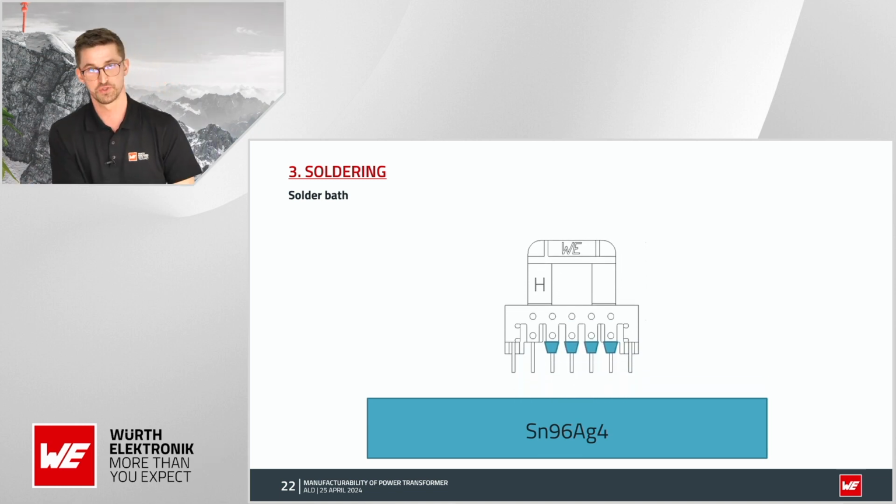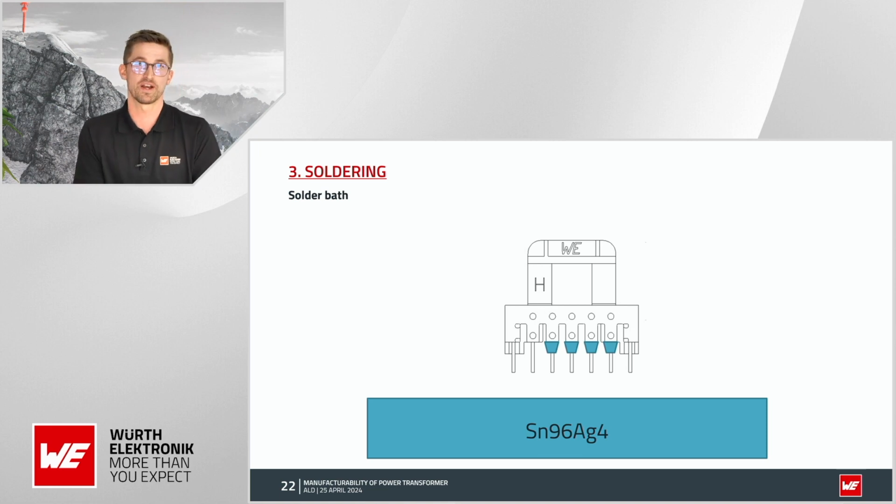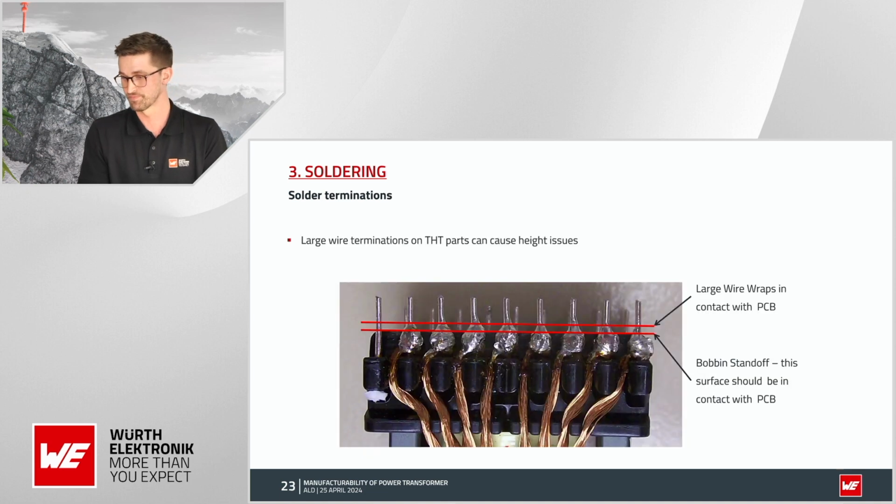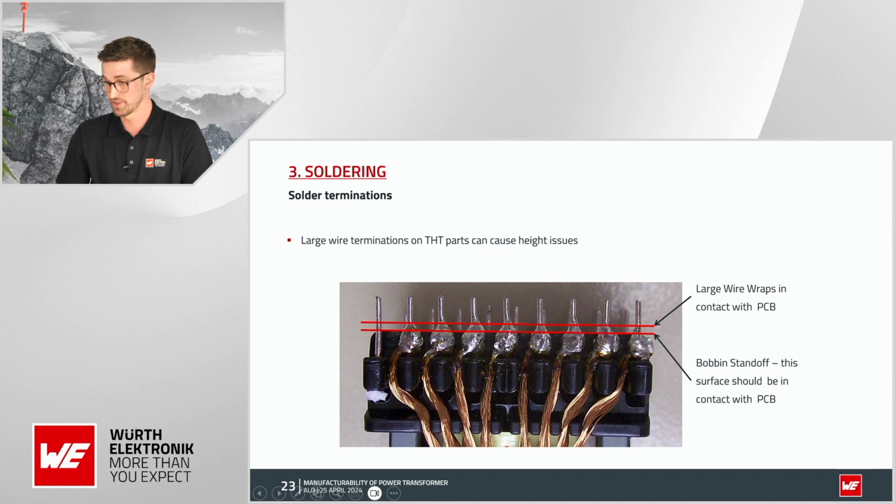There you go, the soldering is complete. Now the wires are well connected to the pins. But let's check this process in more detail. As anticipated before, the termination, the type of wire used, and the amount of tin are important to achieve a good soldering and contact between pin and wires.